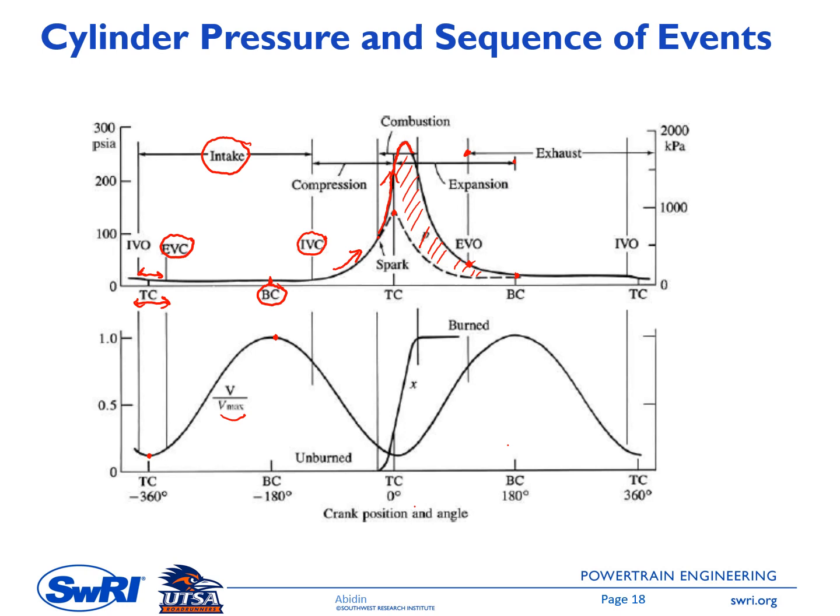So you can see in here at this point we don't have the combustion yet, so it means 100% of the mixture is unburned mixture. Then we have the combustion, and there will be an increase of the burned mass here, and at some point it will hit around 1.